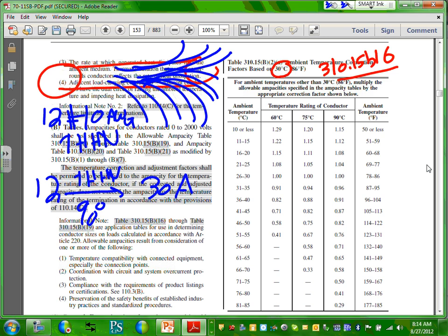Now go to the little table you guys remember, 310.15(B)(3)(a). It says if you have more than 3 hots, you have to derate. How many hots do we have? 12. So for 12 hots, it says 10 to 20. Everybody can see how much? 50. So for 12 conductors, my derating factor is 50%. Which table is that one? This is 310.15(B)(3)(a). Cool? Everybody got that one? Cool.